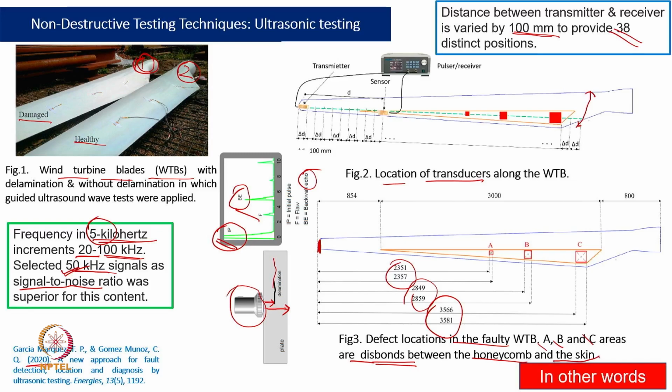Another important thing is that the honeycomb structure starts only after a certain length; at the beginning itself the honeycomb structure is not present. So, if we try to figure out some fault in this zone, it may not be useful at all. They were looking only at the delamination between the honeycomb structure, or support system, and the top skin. These are the important aspects whenever we go ahead with the diagnosis or use a testing method, and we look at only those.